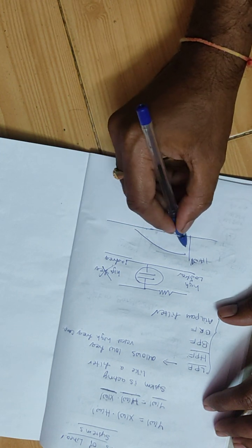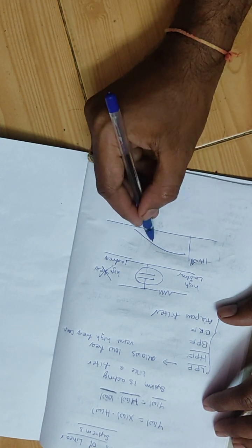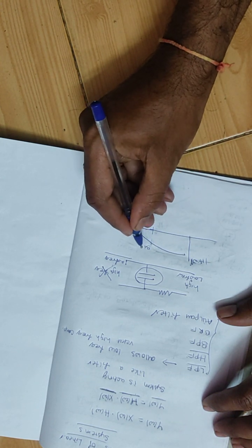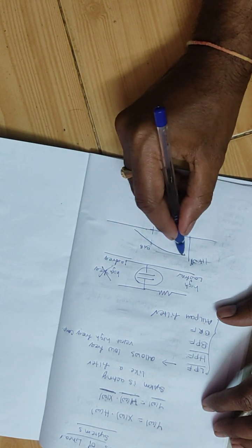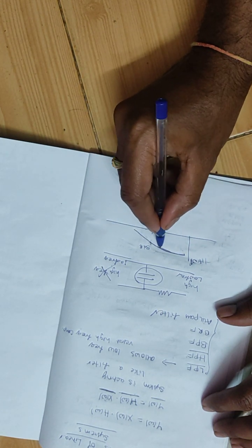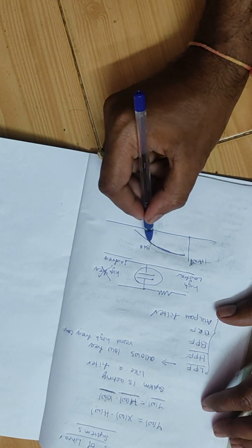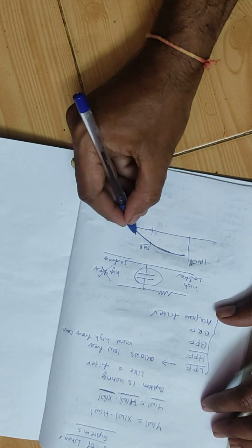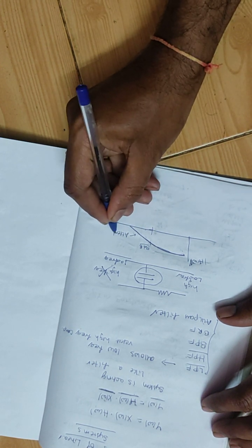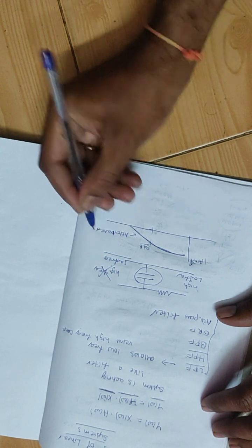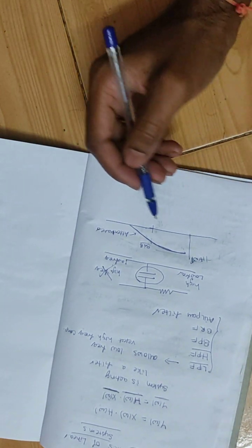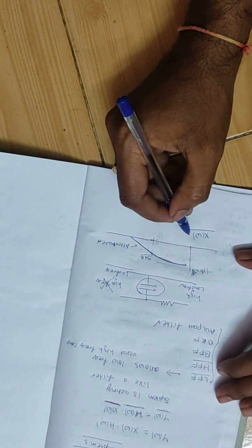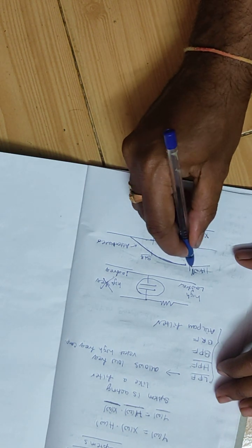So, what I mean to say is, all the low frequencies up to this point, this is the 3 dB frequency, the 3 dB point, and all the frequencies up to the 3 dB point will be passed easily, and all the frequencies above this 3 dB point will be attenuated. That means this X of omega is in some way affected by this H of omega.